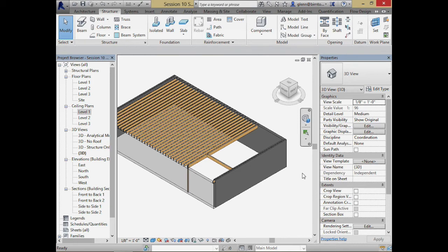That's how you know where to put it. You put it in that spot where it's needed, and that's all it is. If there's one over here, I'm betting I'm going to need one over here too. That's the general rule: wherever there's a very concentrated load. Uniform loads every 16 inches, no problem. Heavy loads, boom, then you need a little bit of spot support.